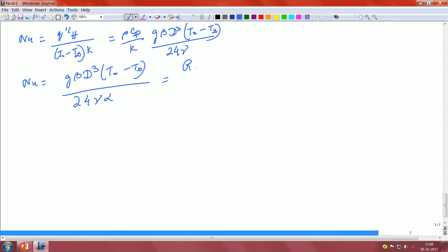So, this is given as Rayleigh number based on the diameter, the separation between the two plates. Separation between the two plates was d. So, the length scale for the Rayleigh number has been taken as d instead of h. So, it is almost similar to the Reynolds number based on d in a pipe flow, right. It is dependent on d. So, that is what the value of your Nusselt number is going to be. Okay. So, the Nusselt number is kind of done.